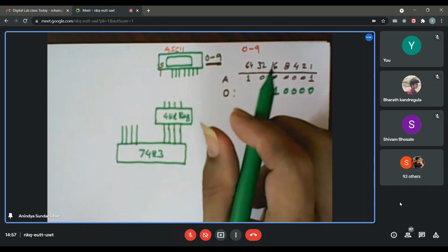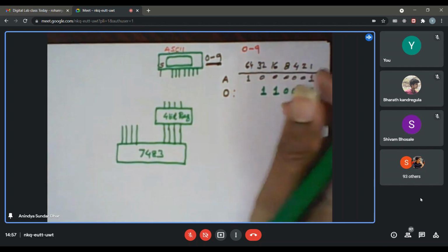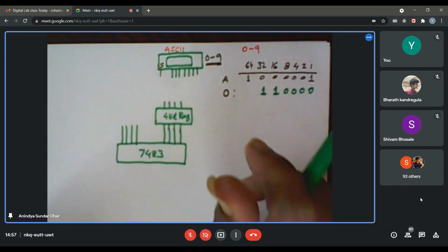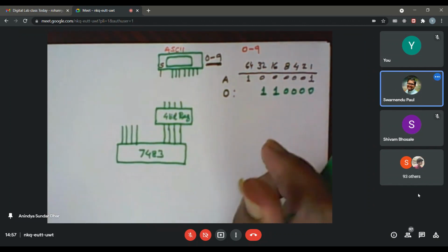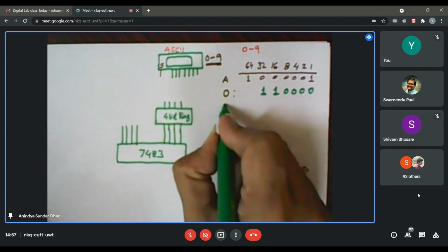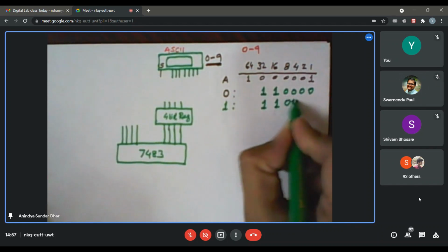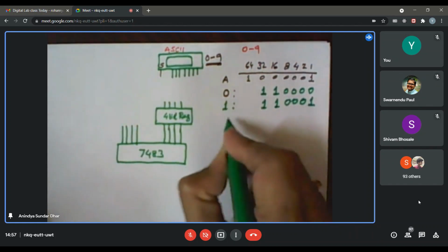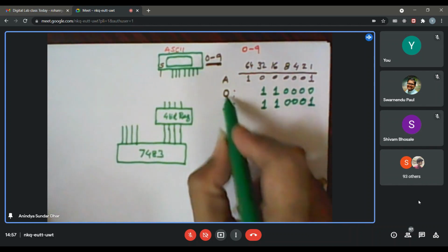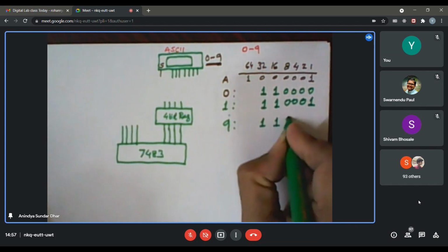Okay. So do you see some pattern coming to your mind, that you can connect this ASCII keypad in some way? We can use the last 4 bits. Okay, if you use the last 4 bits, then let us see, 1 must be 49. So if I press 1, then 32 plus 16 is 48, and it would become 49. In that way, if you add that number to 48, 9 will be 48 plus 9. So it would look something like this, 8 plus 1, 9.